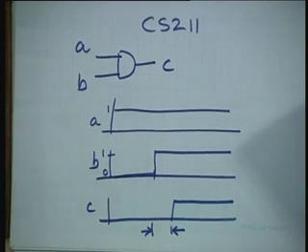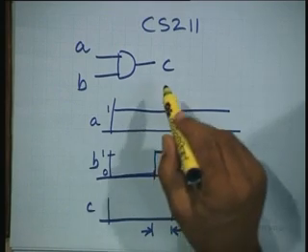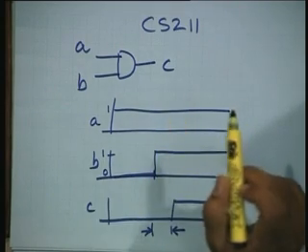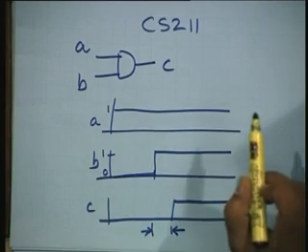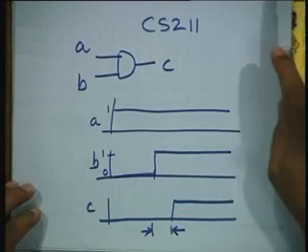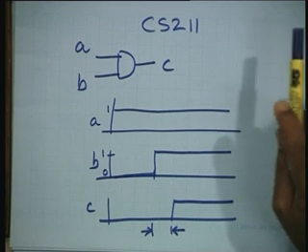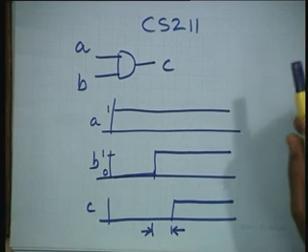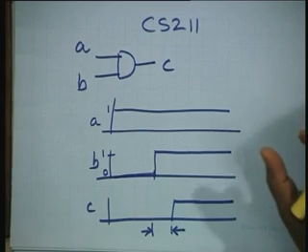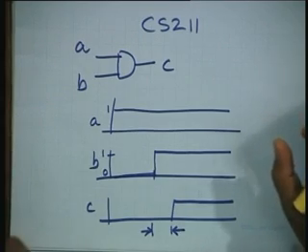Actually, there is also delay in the signals propagating from one point in the circuit to another point in the circuit over the wire. Okay. When you are talking of gates which are extremely fast, where the delays are of the order of picoseconds or tens of picoseconds, then the delays of wires, the time taken for the signal change to propagate over the wire, also become significant and comparable.